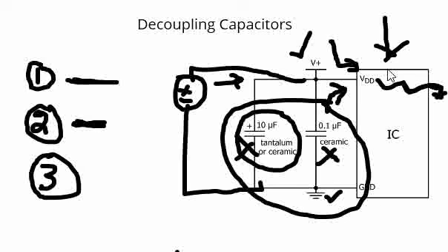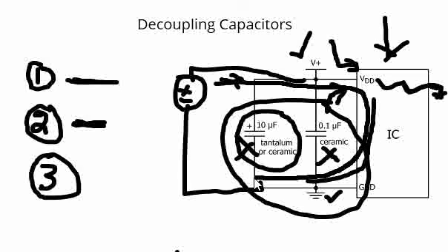Now the noise generated across these terminals and also the instantaneous current will pass from this and return back to the DC supply, which forms a huge loop, and this introduces noise onto the system, right?